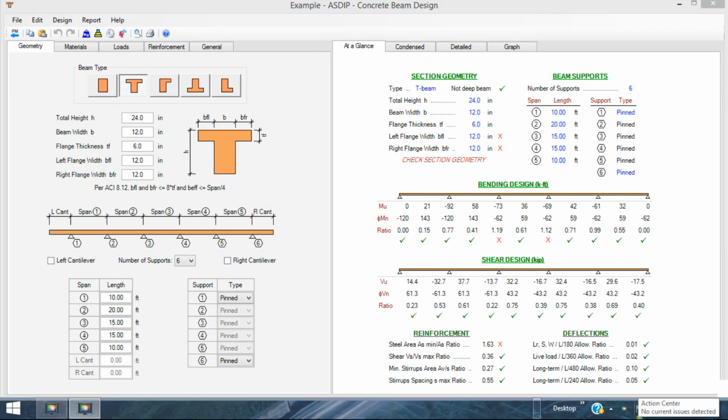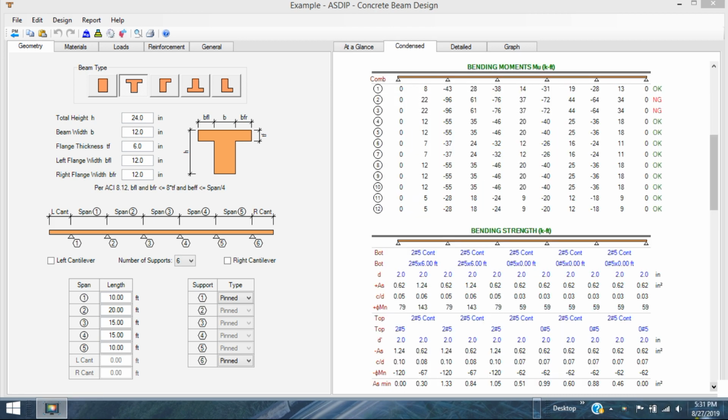When we design a structure, we normally define the loads as a series of load cases: dead load, live load, wind, etc. But normally we cannot apply this load directly into the design process. We need to combine them first.